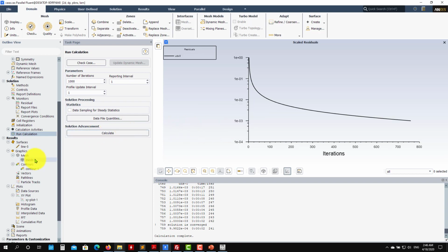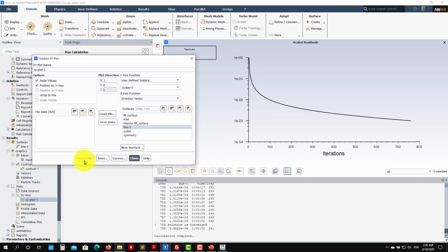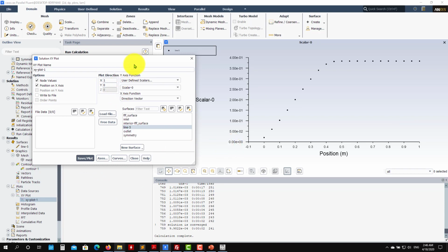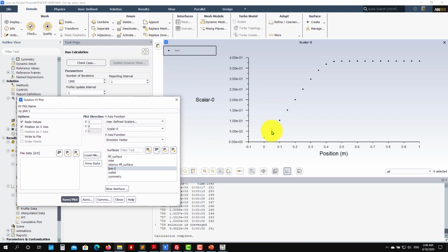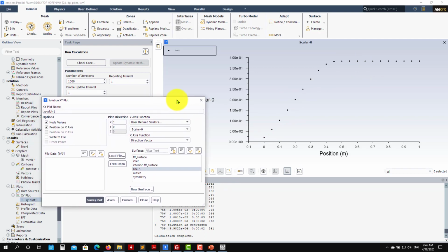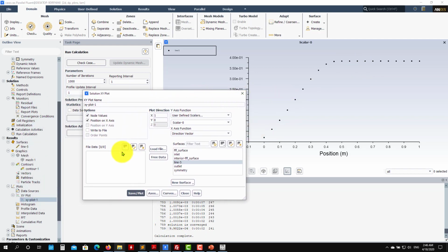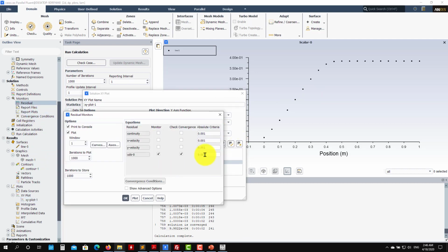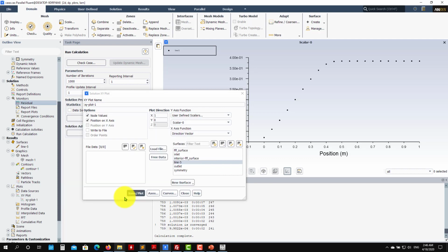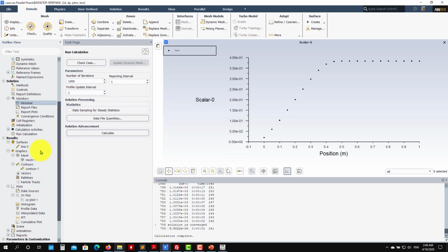Okay, voila, we're here, we plot our solution again. And see that even though we arrived at our convergence criterion, we are still not at the actual solution. So here you see that we have a problem. It is an iterative convergence problem. We need to lower the tolerance here. So if I go to residuals here, I need to reduce this to get to a closer value.